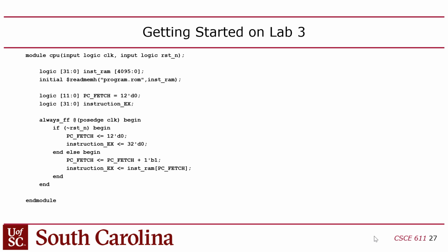Any signal assigned with a _WB suffix should have all of its inputs, the right-hand side of the assignment, be _EX, right? Because those always update their outputs on the clock edge, right? And so whenever those always blocks activate, you're always pushing from one stage to the next, right? So the left-hand side of an assignment should be one stage later than the right-hand side of the assignment, right? And so you should be able to verify that in your code.